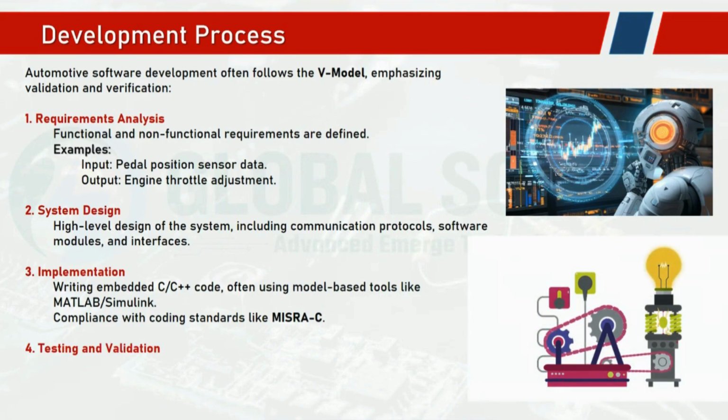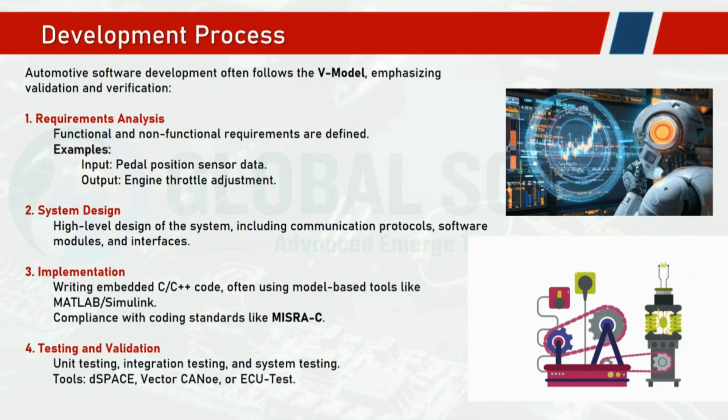And testing and validation. Once the code is implemented for such designs, we should validate with unit testing, integration testing, and system testing. And it should be tested on tools like dSPACE, Vector, or ECU testers. We should ensure that the code is implemented for the specific requirements.